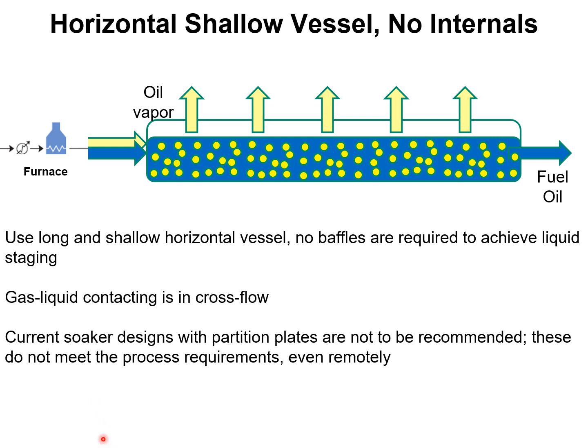I'll leave with the thought that current soaker designs, to my way of thinking, using partition plates are not to be recommended. These do not meet the process requirements for visbreaking even remotely.